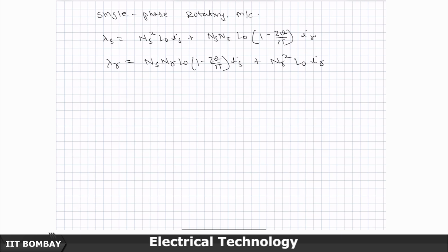And if you recall, n square by R, where R is the reluctance, or n square P, where P is the permeance of the magnetic circuit. If you recall this from our derivation of the inductance sometime back, then you would realize that because of the geometry, and I am going to draw the figure, do not worry about that, we are taking iron as an ideal element.